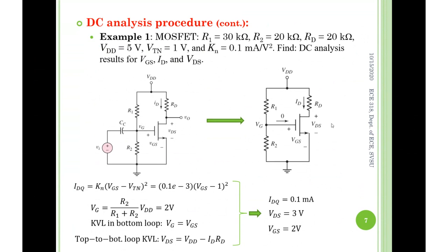When you open up the transistor more, VDS starts to get smaller because it's dropping more voltage across that RD. How would that happen? Your ID won't increase a lot. It's still under control of the transistor behavior.